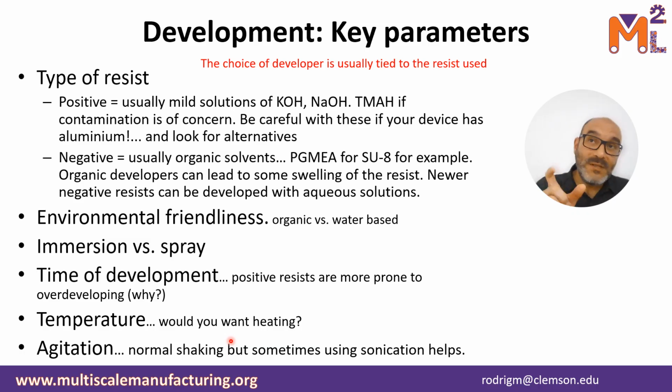Remember that the positive photoresist, when we expose, we only weaken those areas that we expose, but we do not strengthen anything else, right? So you can imagine that that chemical, if you leave it in contact too long with the photoresist, it will of course etch the photoresist that was weakened, but then it will start deteriorating the rest of the photoresist as well, because we did not cross-link it, right?